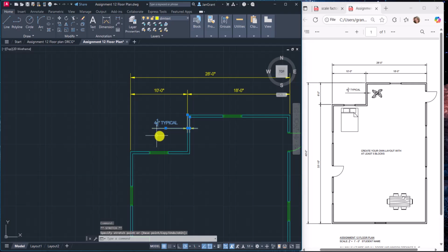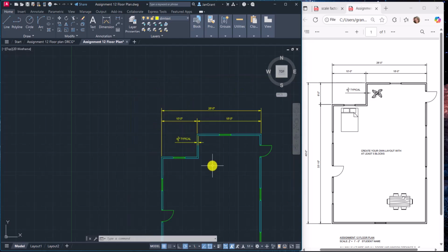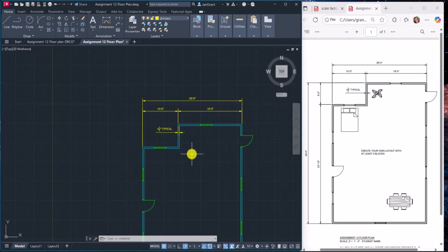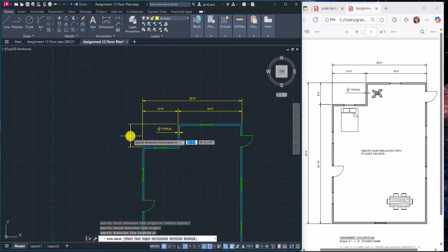I pulled it over to the other side so that I could get something in here, and not a huge detail, but I just wanted to be able to pull it out of the floor plan. All right, so we added text to this 4.5 inch typical. It would normally put just TYP and people would know what that's typical, but I wrote the whole thing in so that you would know. All right, back to dim linear, or back to linear, and we have our 6'2" right there.